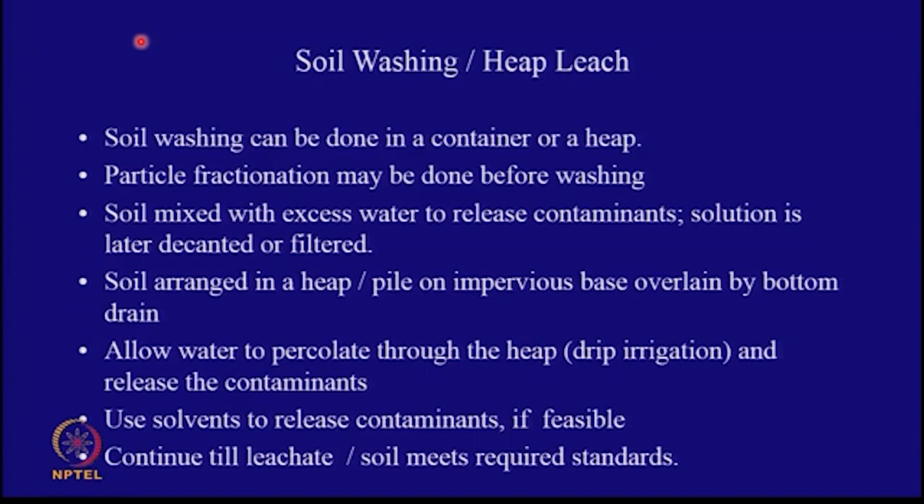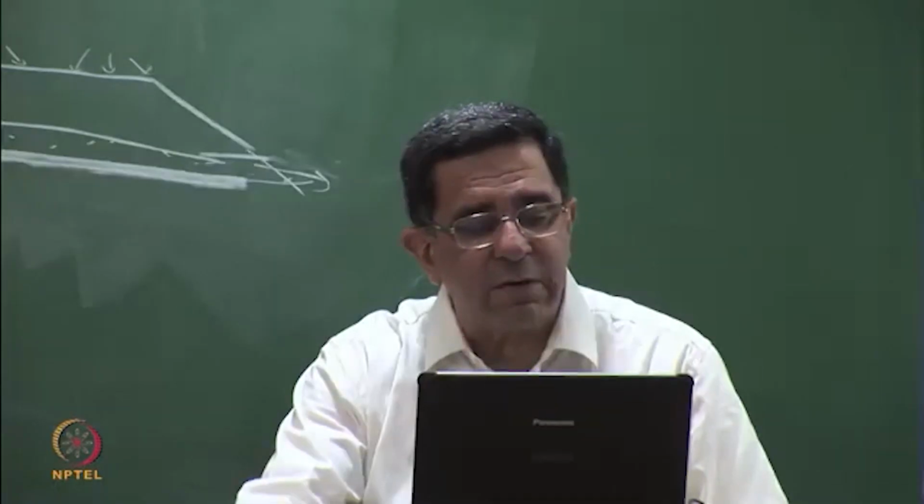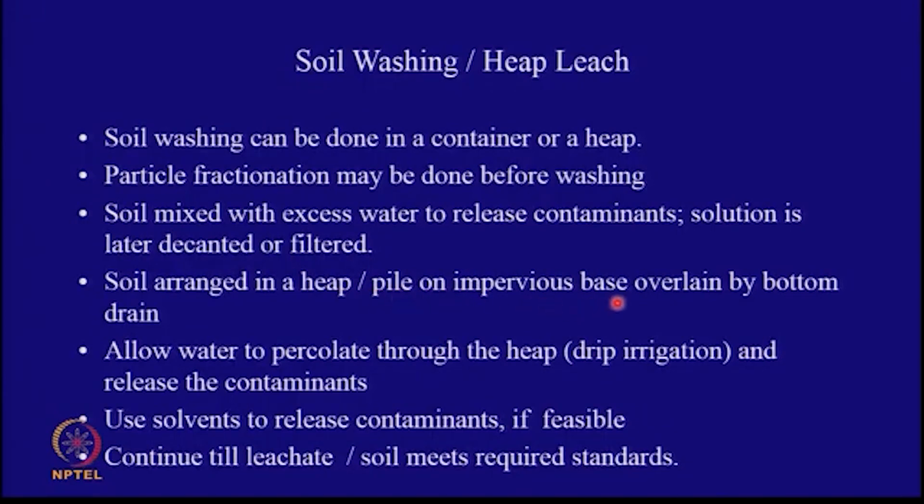So, in a sense, soil washing can be done in a container or a heap. Particle fractionation may be done before the washing. Soil is mixed with excess water to release contaminants. The solution is decanted or filtered. If you are going to have too many fines, you are going to have problems. Then the soil is arranged in a heap on impervious base, overlain by bottom drain. Allow water to percolate through the heap, drip irrigation, and release the contaminants.